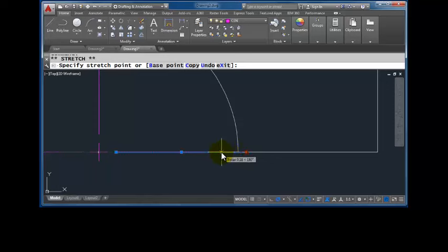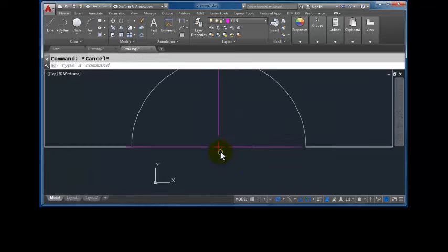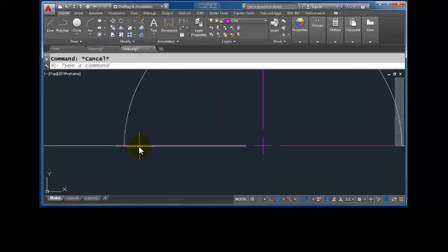And if I double that measurement to 0.125, that will give me the gap that will match my center mark pattern. So I'll do the same on the other side. Select the line, click on the grip, track in the direction I want that to be shortened, and enter the distance.